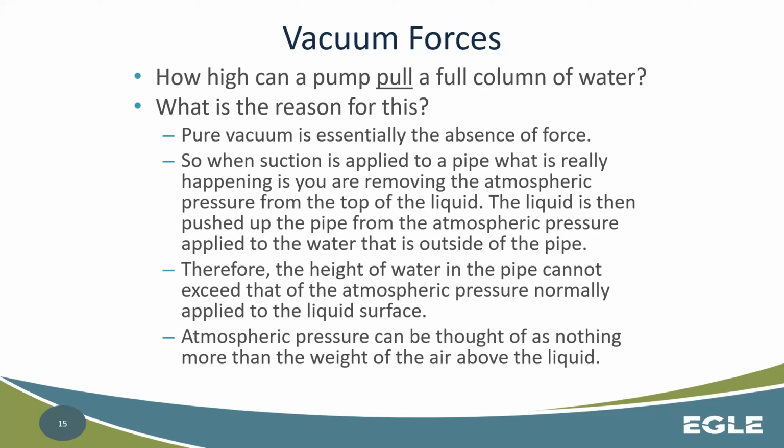So atmospheric pressure is only going to get you to about 32 feet of water height. No matter how big a vacuum you have, if you get to zero air inside that pipe, you have hit full vacuum. Once you hit full vacuum, atmospheric pressure takes over and raises the water roughly to 32 feet.